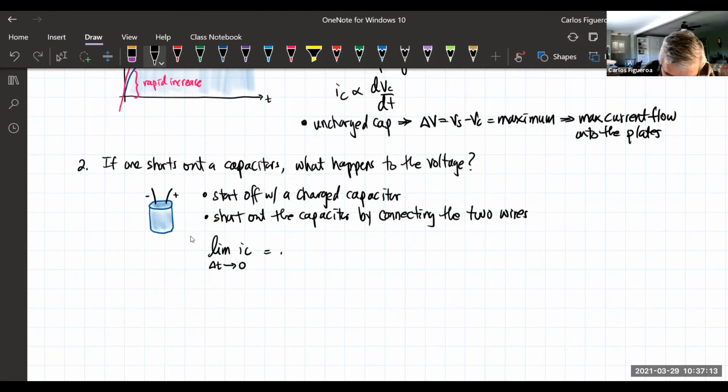What this is really telling me is that the limit of this really means I have C dV/dt like this here. And you can see that in theory, as T gets really, really small, that means I have a very short time to take the voltage of a capacitor and bring it to 0 very quickly. I discharge the capacitor. You can see that this gets very large here.